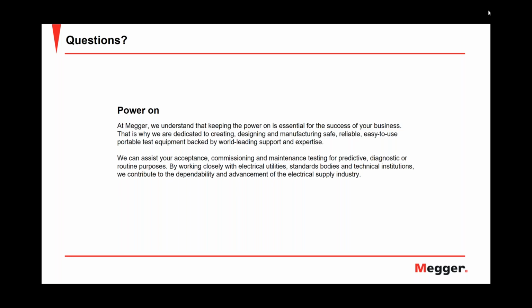So overall, it's a preferred method, and you can see that also when you have a test failure, which can happen. Typically, the fault resistance when you did a VLF test is lower than when you did a DC test. So it's already easier to fault locate typically when you had a VLF test before than when you had a DC test before.